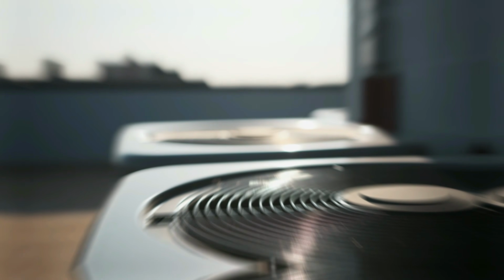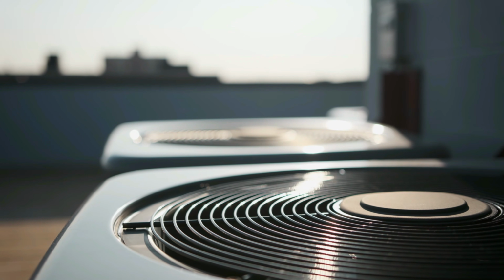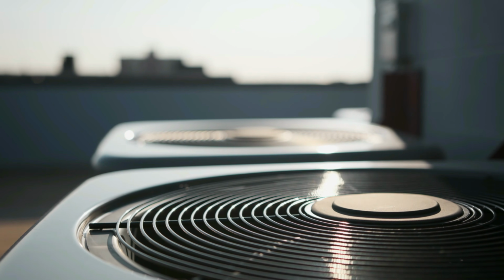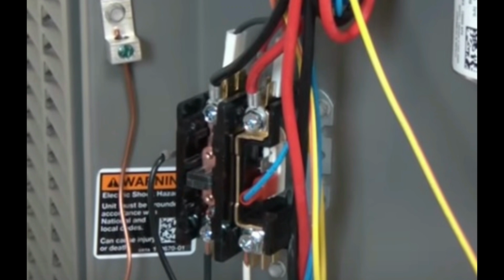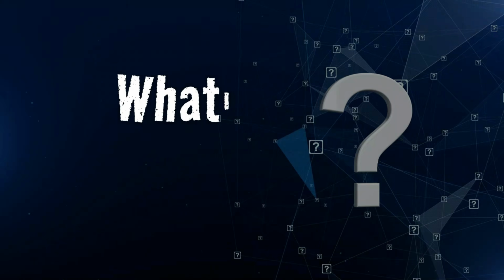You head out to a no cooling call. The customer says the air is blowing out of the vents, but it's not blowing cold. You decide you're going to go out to the condensing unit, and it is completely dead. It's not doing anything at all. So you take the panel off, you look at the contactor, and you notice the contactor's not pulled in. You test for 24 volts, you don't have it. What's your next move?